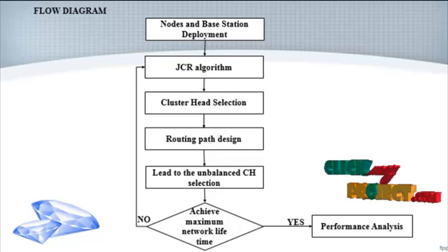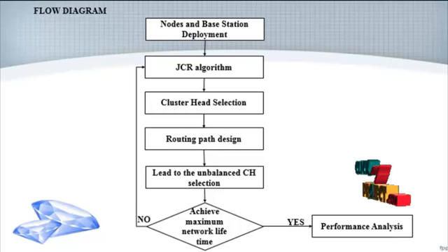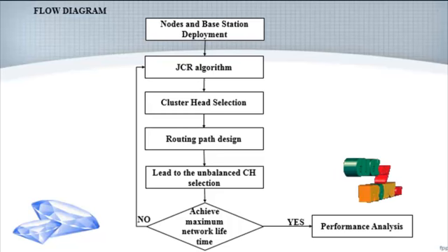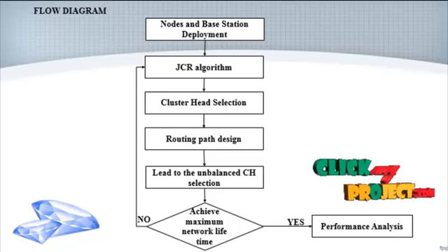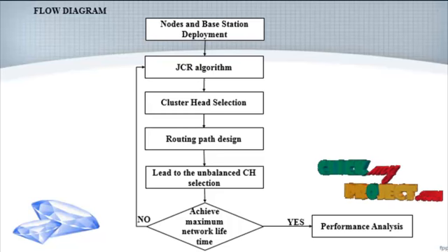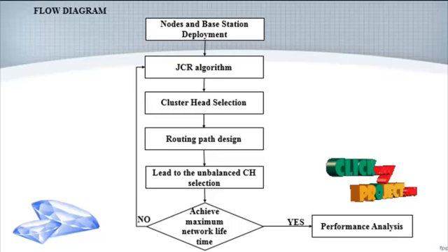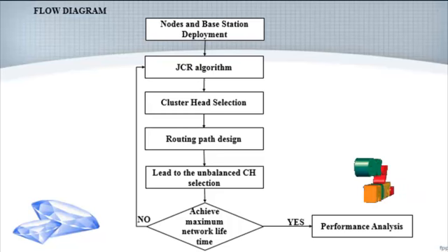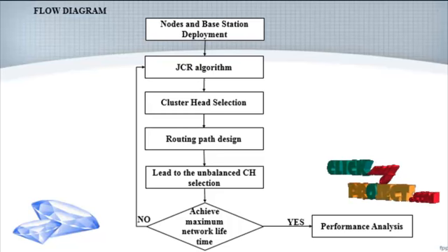The connectivity problem discussed in this paper focuses on the connectivity among the cluster heads. Every node has a maximum transmission range denoted by Rmax. This motivates the requirement of keeping network connectivity within the limitation of Rmax. The critical transmission range, that is, the CTR, is less than Rmax. The CTR is defined as the length of the longest edge of the Euclidean minimum spanning tree built on the nodes. If this assumption is not satisfied, the network will be disconnected even if every node is selected as a cluster head and uses its maximum radio power for data transmission. This assumption can be satisfied by reasonable node deployments.